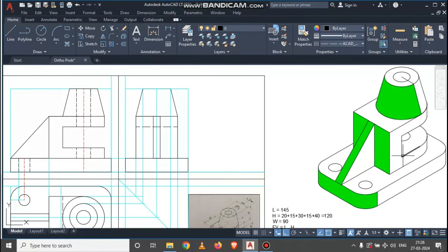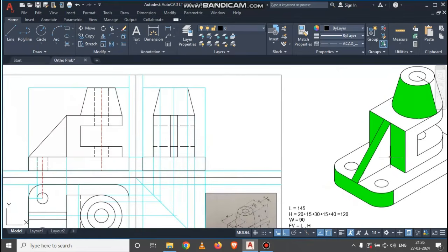Okay, in a similar way we are going to represent this corner point as well in the direction of the observer, so that we will get somewhat over here, and again from that point we are going to represent the total width equal to 60 mm. And the same we can have by projecting this corner point in a horizontal manner. So this will be the starting point and this will be the end point for the width equal to 60 mm. So we are done with these two hidden surface lines, for this corner and this corner.